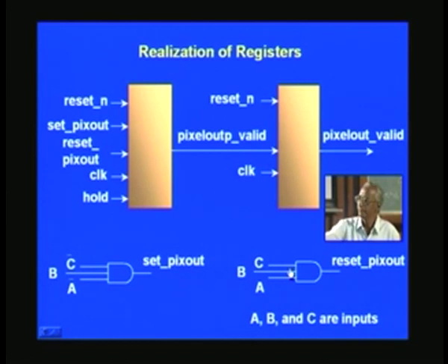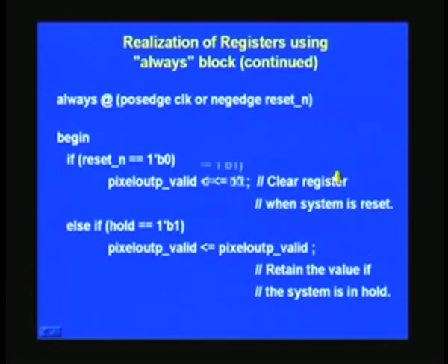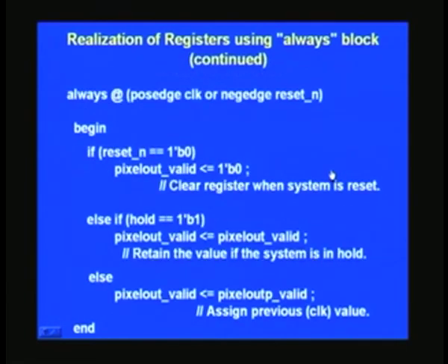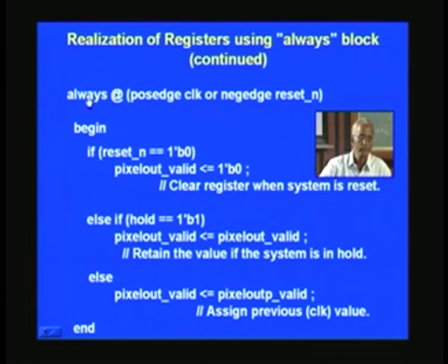And we will now see this flip flop implementation, which is very much similar to this. So once again we use always at positive edge of clock or negative edge of reset, and you notice that when you go through the course, you will get again and again the very same structure all through, and that is the beauty of this structure. Especially when you want to redesign something or even start on a new design, all you need to do is save your earlier project's file and simply rename it to suit the new design. So that way it helps.